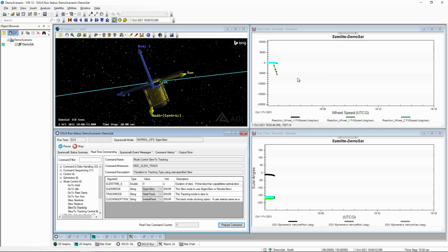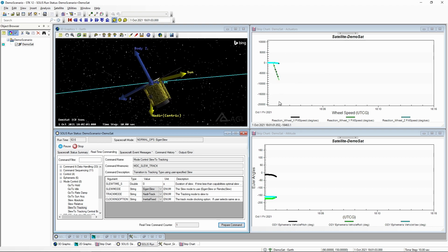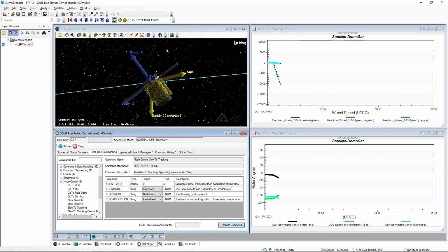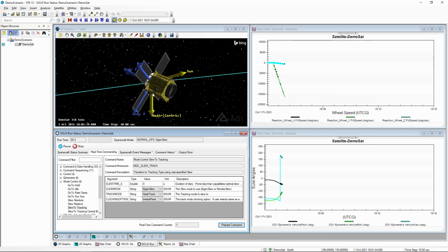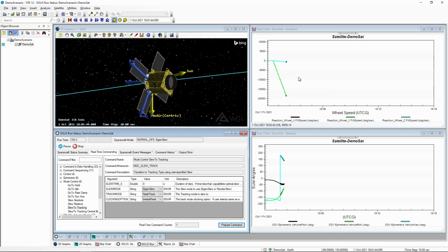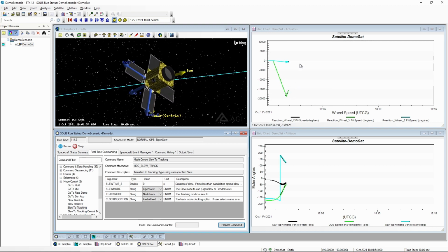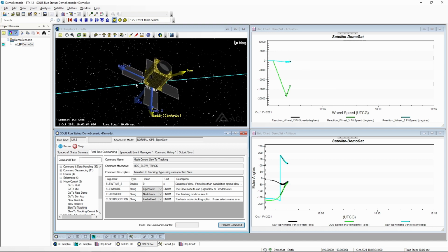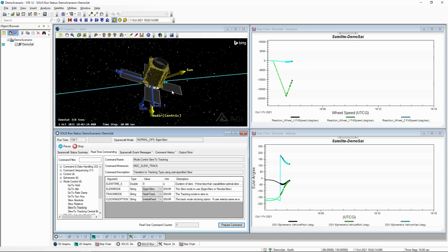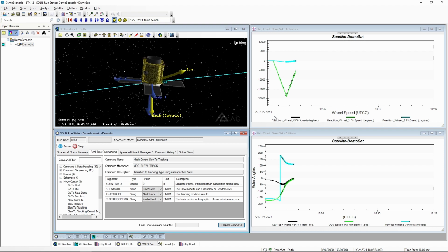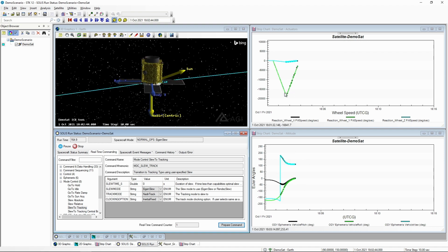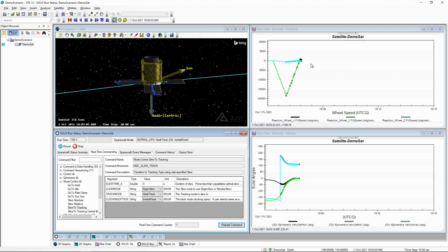Here's our reaction wheels responding, spinning up to change the orientation of our satellite. However, we should be in control and come to rest at this nadir vector and see the reaction wheel speeds come down and rest at a value of whatever is required to keep the spacecraft in this orientation that we've requested. So as expected, we see our attitude change, we see the reaction wheel speeds go up and come back down, and now they're settling out into this steady state position.